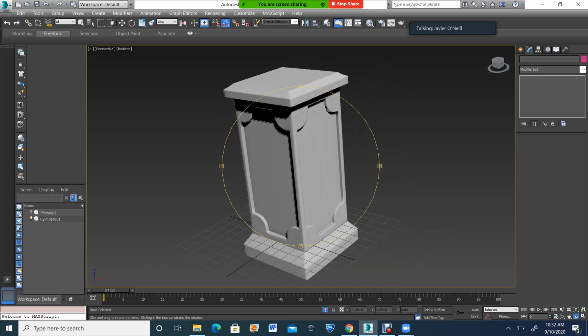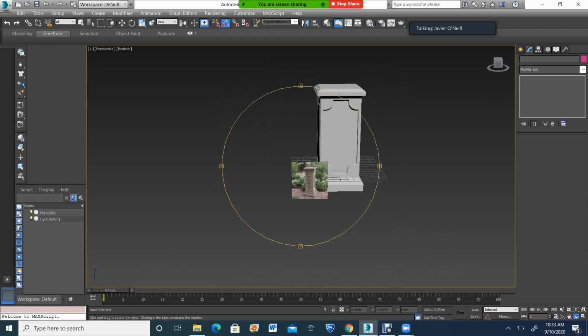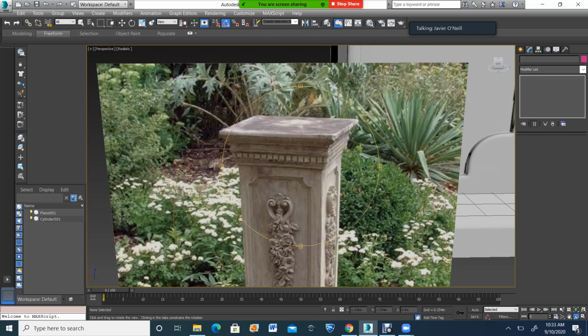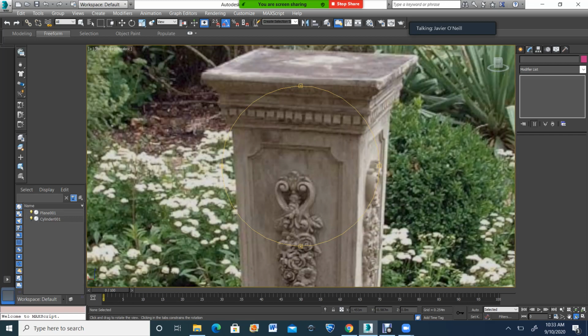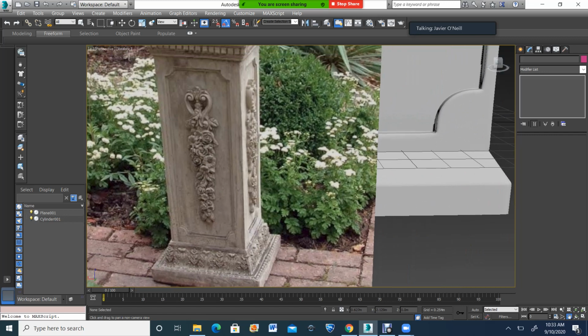And the thing is, whenever you create a high poly item that you're going to use for baking and such, you don't have to do it as one complete object, because that's a pain. You can make some of these details and float them on the surface. For example, this little floral pattern right here, there's no reason why you need to cut that into the mesh. You could do it separately and lay it on top. As long as your low poly mesh has that detail made into the mesh, then when you do the baking process, it's not going to be much of a problem.